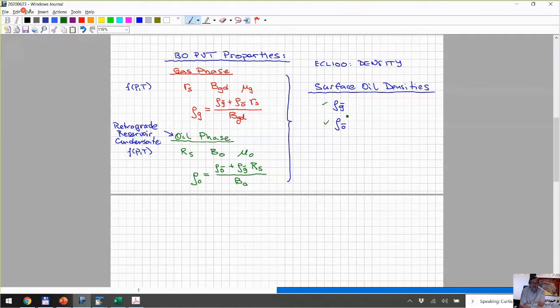I suspect that the pressure difference between the upper part of the hydraulic fracture and the lower part of the hydraulic fracture would be very small because of the high conductivity. You might get some gravity segregation during flow, but I would not suspect very much. Again, why speculate if you can calculate?